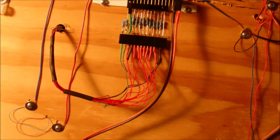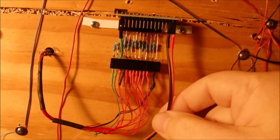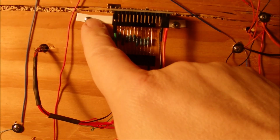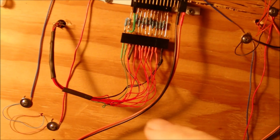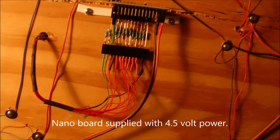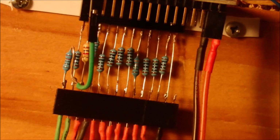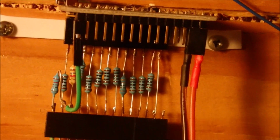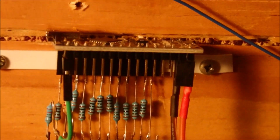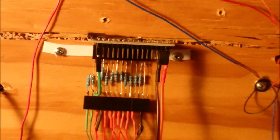And here we are under the board. Got all the wires down through that little hole. There's my power supply, 4.5 volt power supply coming in, and screws on either side there to attach it to the bottom. And here's all my wires coming out of there. And you can see all the resistors in there. Note the one wire on the far right there is the ground wire. There's no resistor on that, so that's just a straight wire. No resistor on the ground wire there.